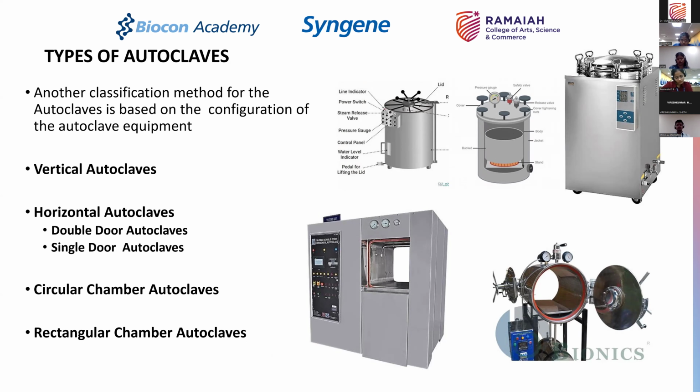So vertical autoclaves are used, of course, when you're talking about a modern day autoclave. For example, they look sophisticated like this. They don't look like this any longer. They are with a proper enclosure. They come with a good control system, as I said. They have an inlet for water, so you directly connect a water source here, and there will be a level controller inside the tank which will make sure that the level is never out. Because one of the important things in a vertical autoclave, just like our pressure cookers at home, you have to make sure that the water is always present there.